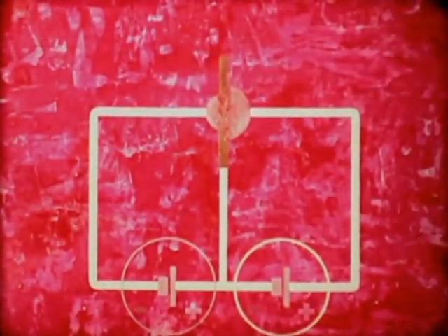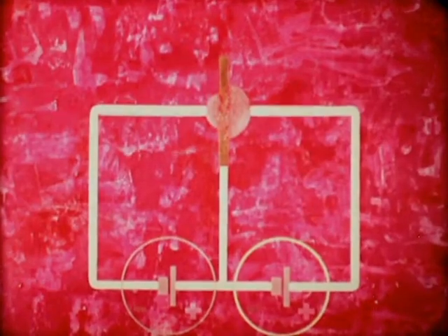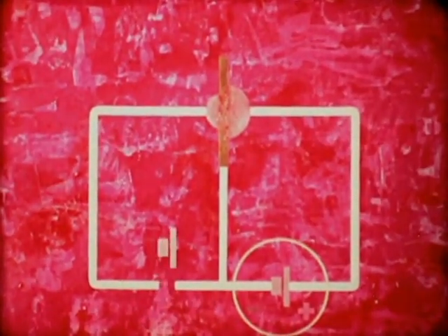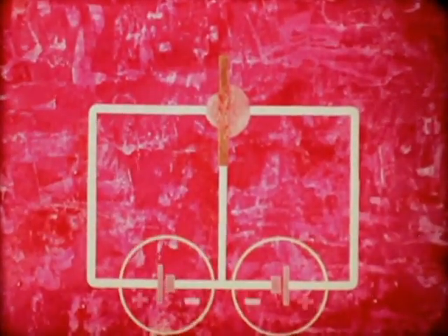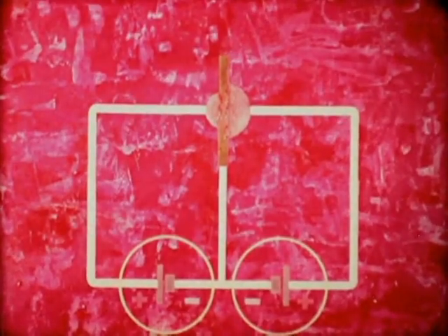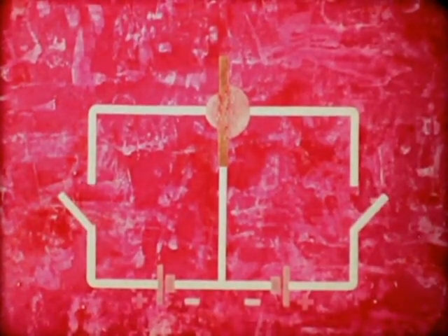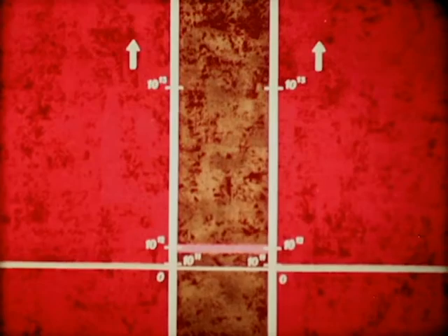The final state to be examined is achieved by reversing the polarity of the battery in the emitter-base circuit only. When both circuits are interrupted, the barriers assume a width corresponding to the equilibrium condition, and the minority concentration graphs become horizontal.